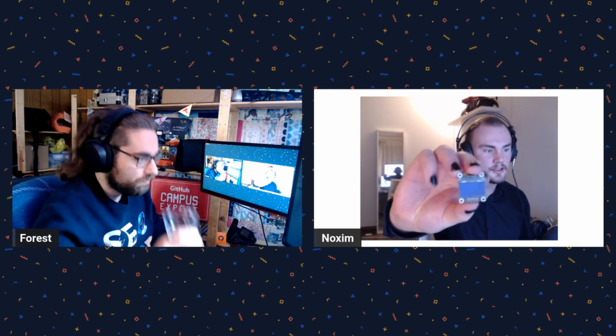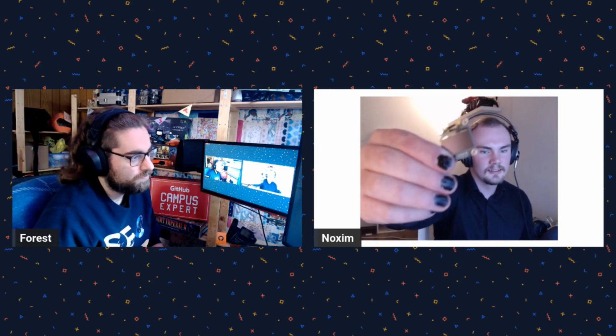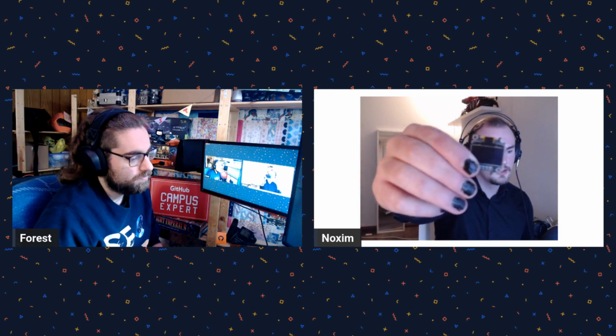But with some other stuff, for example, if you add the driver for this display, now it balloons up, and I'm up to like 12K, which doesn't leave much headroom. There are some things you can do to improve it. For example, this display has 8,000 1-bit pixels, so it already takes 1 kilobyte of memory to store the frame buffer. But you can do some tricks. You can, for example, not store a frame buffer and generate it as you write it out to the display. Oh, interesting.